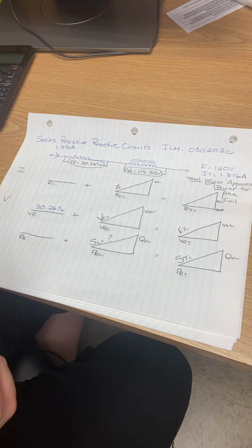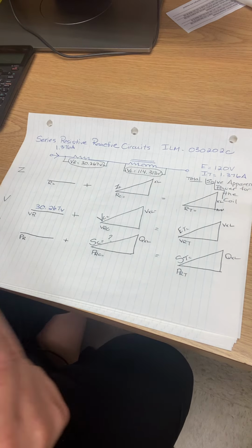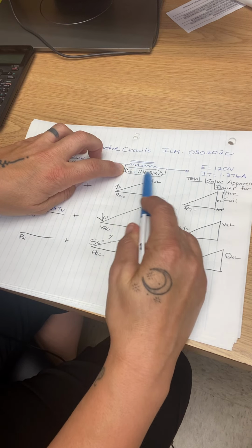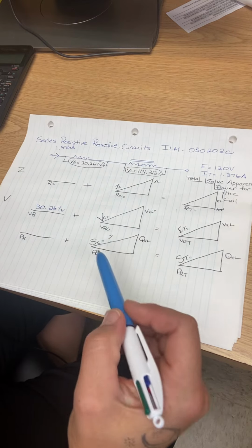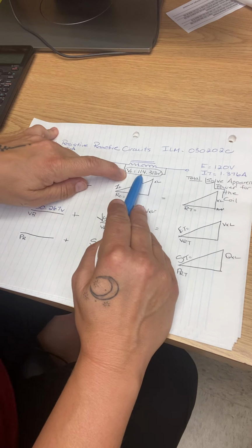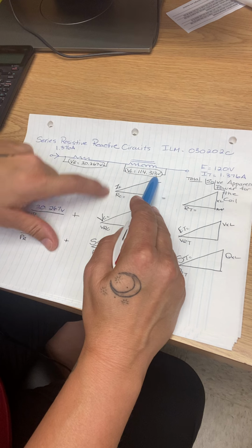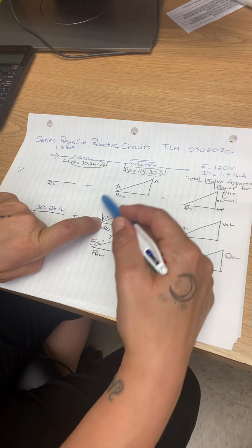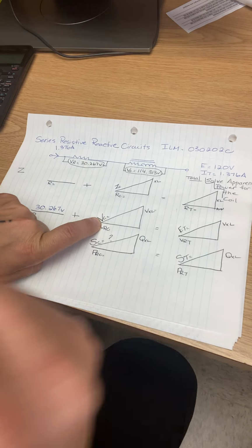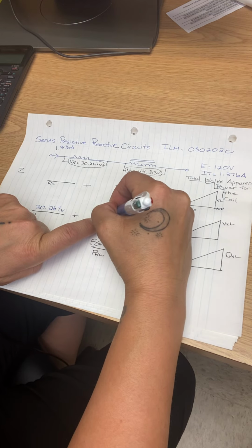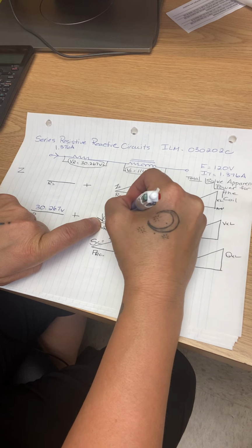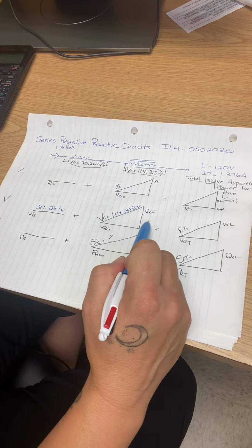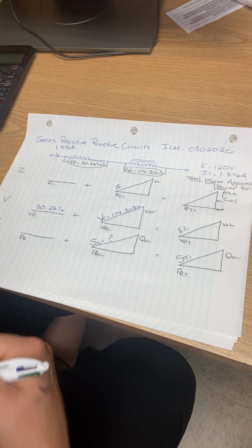You're metering your volt drop across the two leads of the motor, which would give you the volt drop across the entire portion of the inductor, right? So when they say the volt drop across the coil is 114.313, you need to recognize that volt drop represents the hypotenuse of your voltage triangle for that coil. And that is a very common mistake made by many apprentices. They will take that volt drop and either put it in the resistive portion or in the inductive reactive portion, and that just throws off everything.